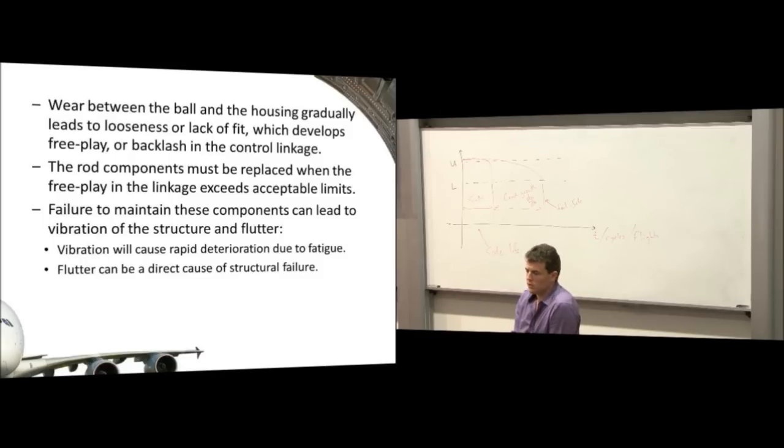And if those connections start to wear, they all have a little bit of free play in them. They all get a little bit sloppy, so that you end up with the ability for there to be chatter in the control surface. So even if the pilot's holding the stick still, the control surface has some free play in it because there's slack in the system. Now, that's a problem for two reasons. Just the vibration of it in the airflow will cause fatigue, and also can lead to a more catastrophic phenomenon, which is called flutter, which we'll talk about in the last lecture of this semester.